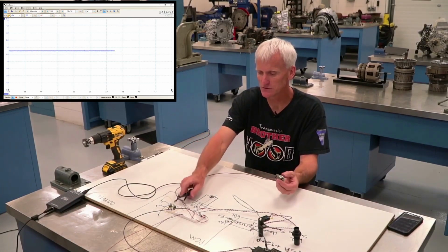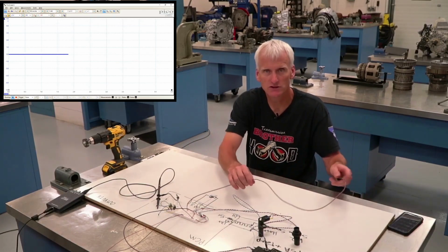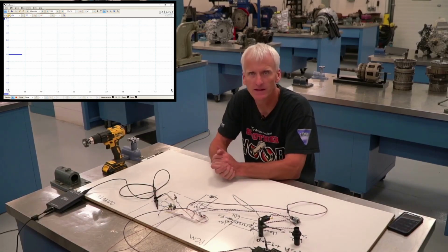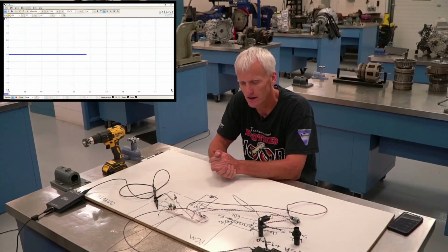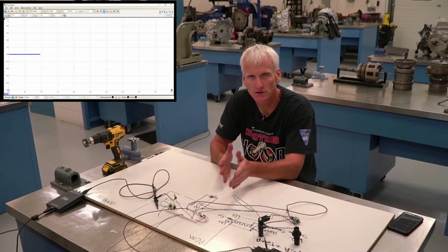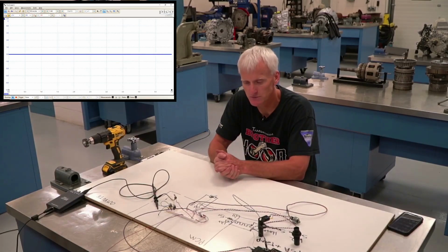And some transmissions are going to need to know that, because if they can adjust, they might need to adjust the pressure in the transmission based off of the load that the engine's putting out. And they want to know specifically if the pressure that they're trying to achieve, they're actually getting. So they might put a pressure sensor in this transmission. Not all transmissions have pressure sensors, but there are plenty of them that do.